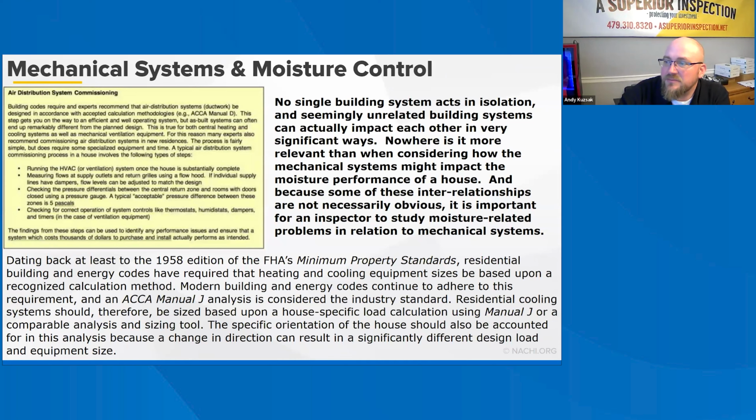Inadequate air returns cause moisture problems. Most central return systems do not provide adequate pathways when interior doors are closed, because door undercuts do not provide enough flow area for the return air. As a result, some interior spaces become pressurized and others become depressurized. Both of these conditions can drive air leakage and moisture transfer.